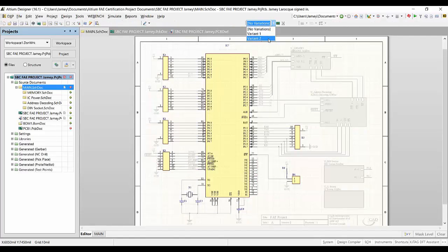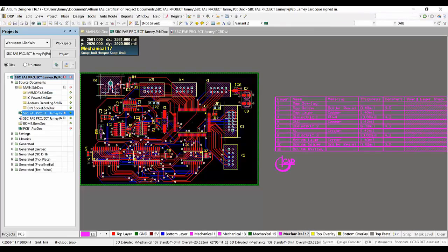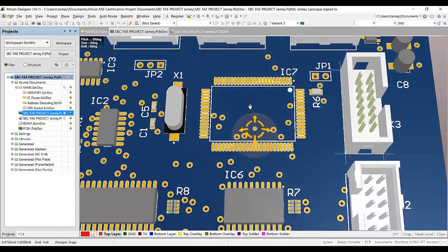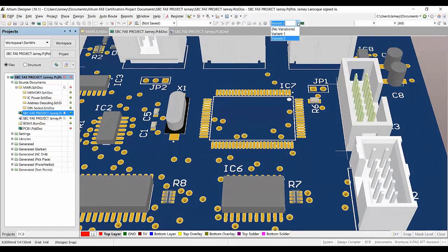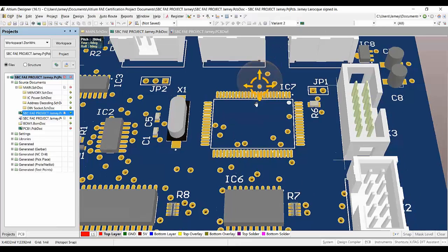There is also support for variations to component overlay information on the PCB, for example, changing a component's comment. This type of variation requires two overlay screens to be produced, resulting in two different bare boards. This type of variant is referred to as a fabrication variant.